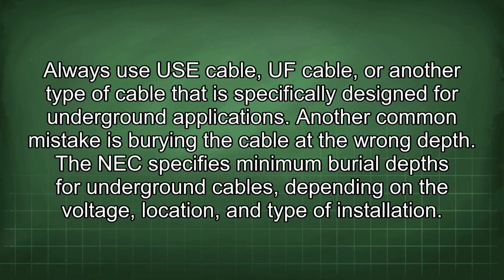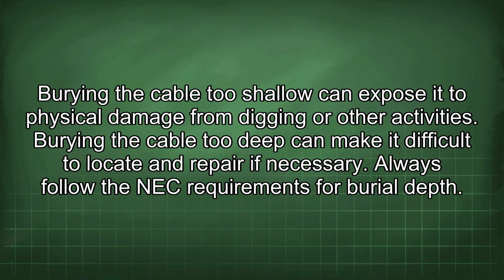Another common mistake is burying the cable at the wrong depth. The NEC specifies minimum burial depths for underground cables depending on the voltage, location, and type of installation. Burying the cable too shallow can expose it to physical damage from digging or other activities. Burying the cable too deep can make it difficult to locate and repair if necessary. Always follow the NEC requirements for burial depth.